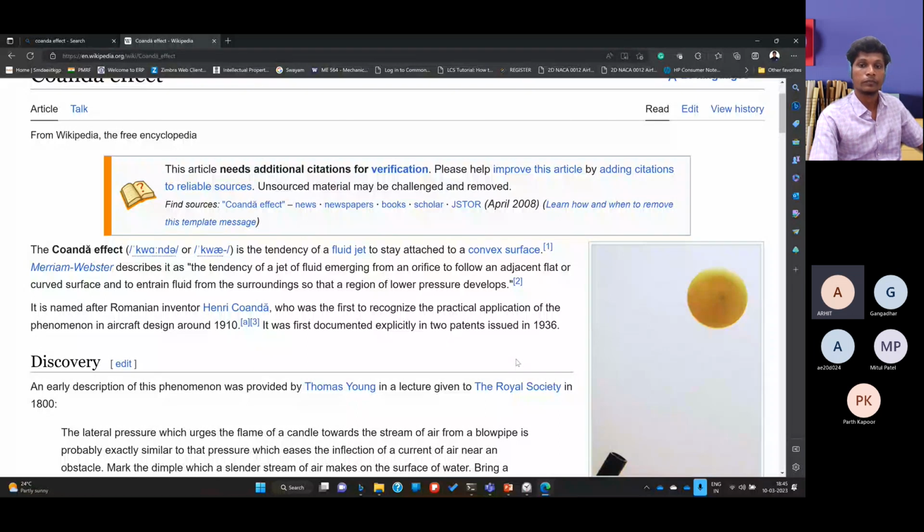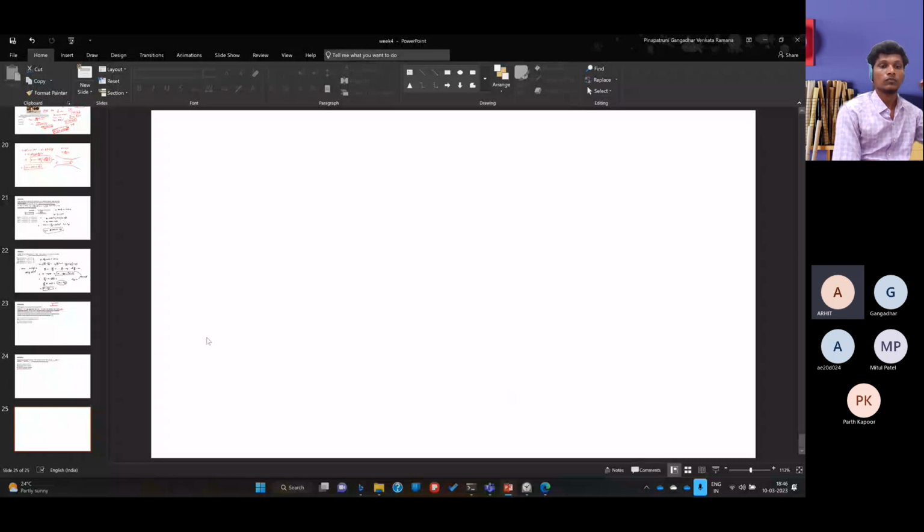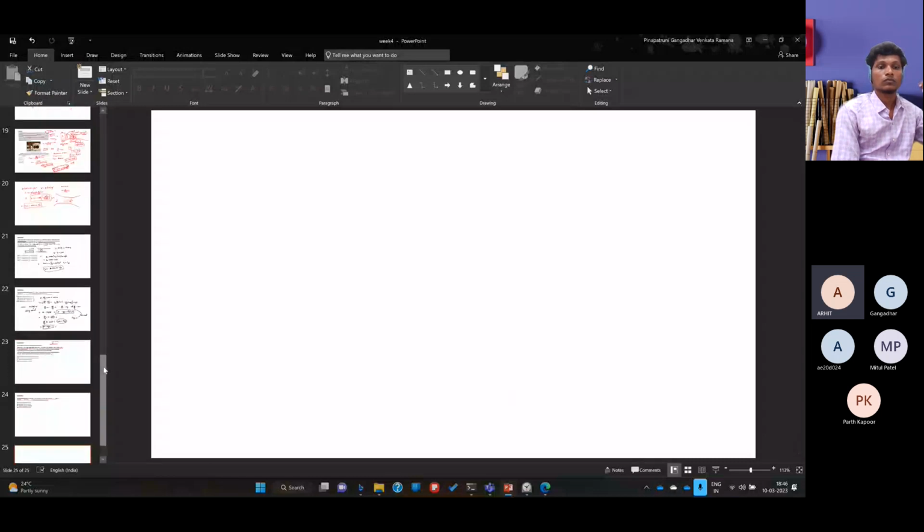Sir, but in the case of stalls, the formation of wakes near the trailing edge, why basically do those wakes form? Due to the adverse pressure gradient forming near the trailing edge. Is that adverse pressure gradient more than the ambient pressure gradient that forms the wake near the trailing edge?